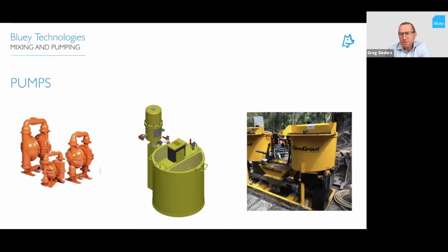So these are just some images there. The image on your left is a diaphragm pump. These are very versatile pumps and good for a wide range of different applications. Good for fast setting grouts. They're very simple, not much can go wrong with them, and good for high volumes as well.